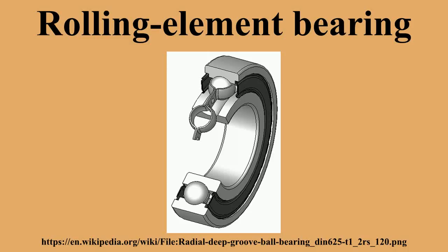There are also many material issues. A harder material may be more durable against abrasion but more likely to suffer fatigue fracture, so the material varies with the application. And while steel is most common for rolling element bearings, plastics, glass, and ceramics are all in common use. A small defect in the material is often responsible for bearing failure. One of the biggest improvements in the life of common bearings during the second half of the 20th century was the use of more homogeneous materials, rather than better materials or lubricants.